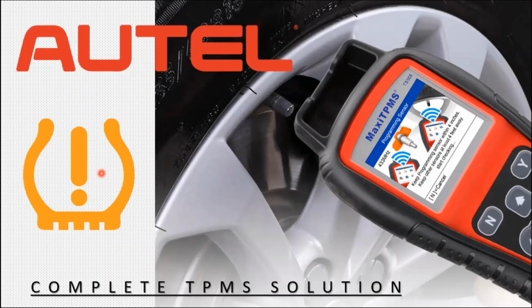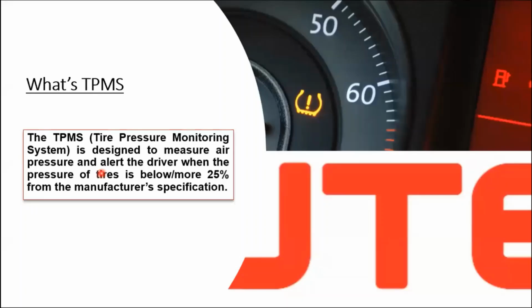So let's begin with defining what a tire pressure monitoring system is. The tire pressure monitoring system, or often in short referred to as TPMS, is a system designed to measure air pressure on the wheels of an automobile and alert the driver when the air pressure of tires is below or more than 25% from the manufacturer specifications.